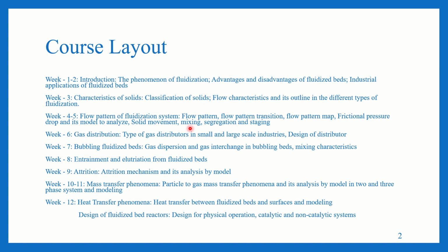These are the contents up till this week. In the coming weeks, we will deal with gas distribution and special focus on bubbling fluidized beds, because in some applications it is ideal to use bubbling fluidized beds. At the same time, we need to control the bubble formation. When dealing with gas-solid fluidized beds, bubble formation poses some serious issues with mass transfer. So bubbling fluidized beds, entrainment and elutriation from the fluidized beds, attrition, mass transfer phenomena and heat transfer phenomena will all be dealt with in the following weeks.